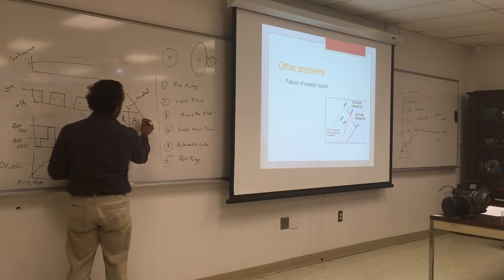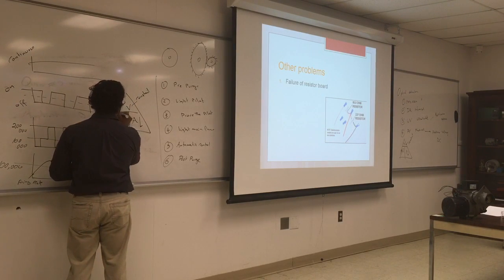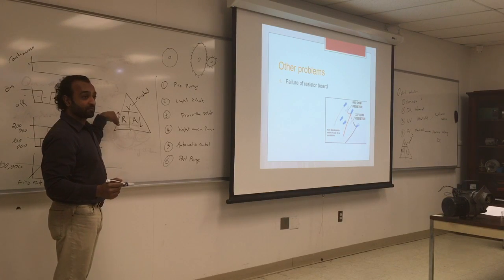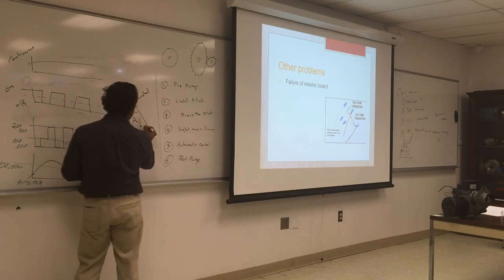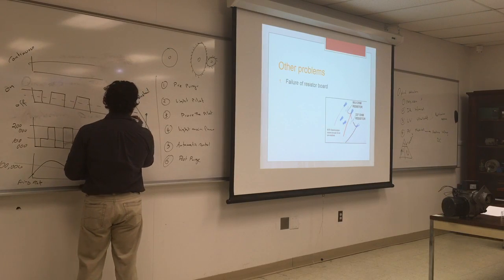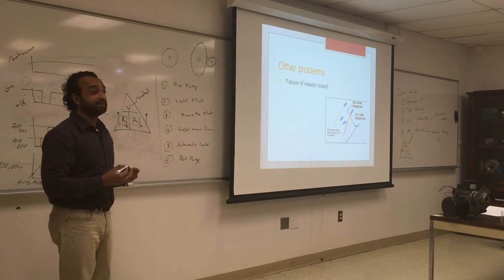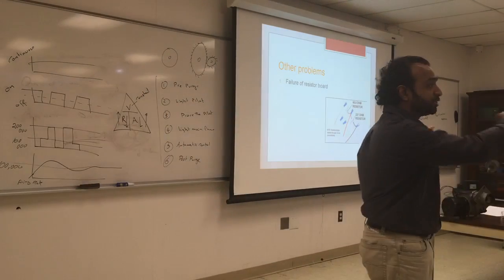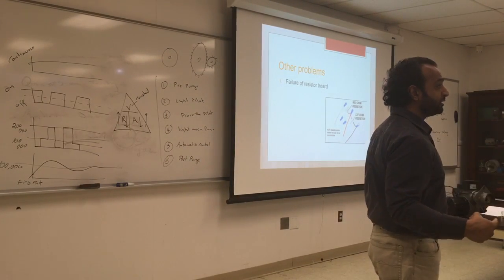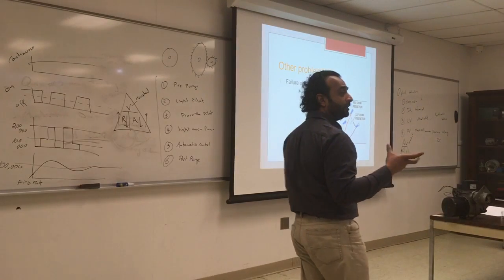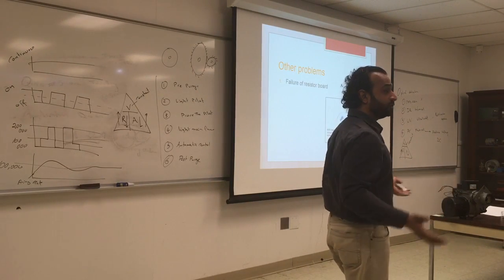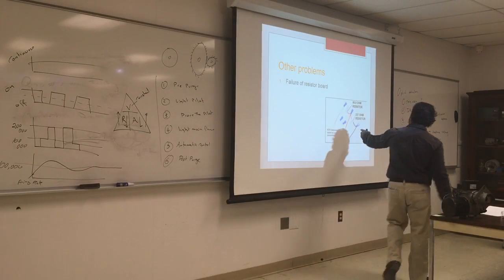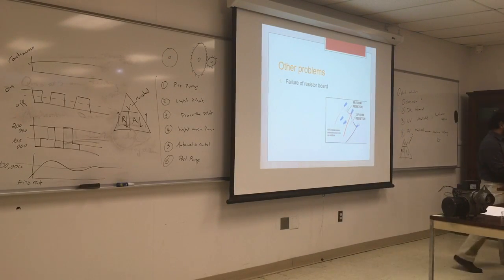Exactly. If I want to bring this down, I have to increase the resistance. And vice versa, if I want to increase the amperage, I will decrease the resistance. This is what is happening in the cad cell. It has high resistance, no amperage going through to turn on the boiler. So I expose it to the light, decrease the resistance, and we open the flow. It's kind of like opening a flow valve. That's why we have resistances in some of those connections.